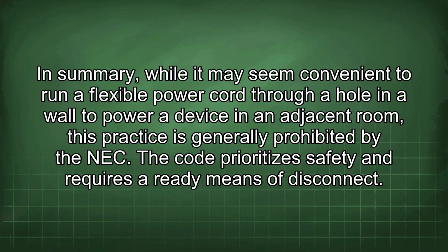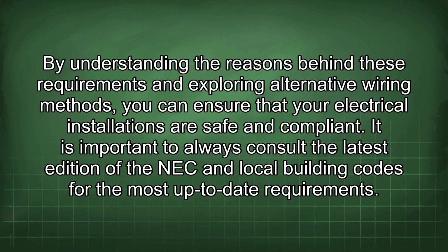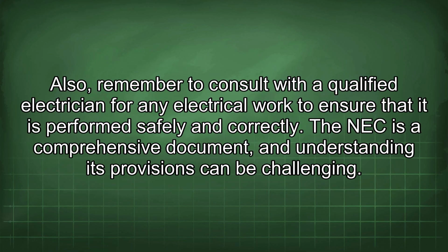In summary, while it may seem convenient to run a flexible power cord through a hole in a wall to power a device in an adjacent room, this practice is generally prohibited by the NEC. The code prioritizes safety and requires a ready means of disconnect. By understanding the reasons behind these requirements and exploring alternative wiring methods, you can ensure that your electrical installations are safe and compliant. It is important to always consult the latest edition of the NEC and local building codes for the most up-to-date requirements. Also, remember to consult with a qualified electrician for any electrical work to ensure that it is performed safely and correctly.